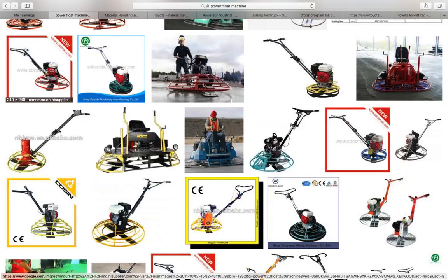Also, make sure that we have adequate ventilation anytime we're using any gas powered tools. Make sure we minimize the risk of any type of carbon monoxide poisoning or LELs. Keep our hands and feet away from any type of cutting ends, saws, grinders, trowel machines, whatever it may be. Store tools properly when they're not in use, and in appropriate containers if necessary as well.